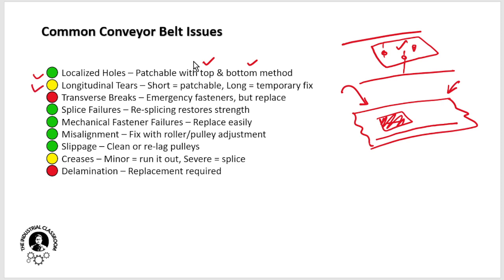In major cases of long tears, we generally go for belt replacement or piece addition. Next, in case of transverse breaks, remember, whenever this is your conveyor belt and we have a transverse cut here, these cases are very urgent, and these require deep focus because repairing it is our high priority. We go for fastener repairs in such cases. Here repair strips won't work. Only repair strips would be a foolish job, we would say.